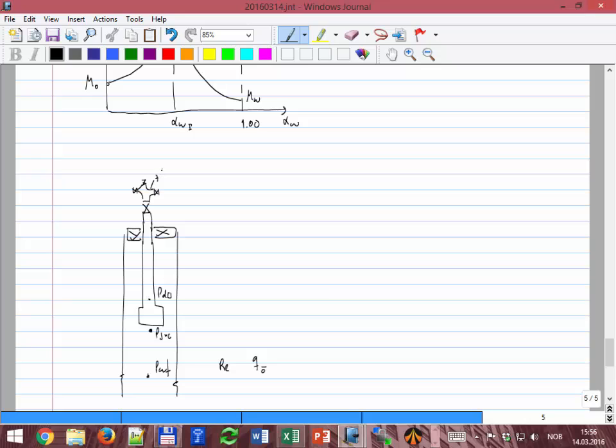Okay, they're going to be operating, because remember that depends on the processing facilities, that depends on the separator, and they are going to try to keep that pressure all the time at 7 bar. So I have the pressure, I have the rate, and I can calculate counter current. I have P2 and I can calculate P1, which is the P at the discharge of the pump. Okay, and with these two P's I can say the delta P of the pump that needs to deliver P discharge minus P suction